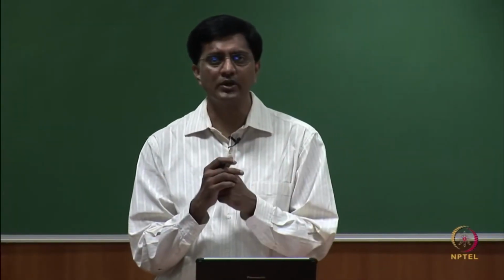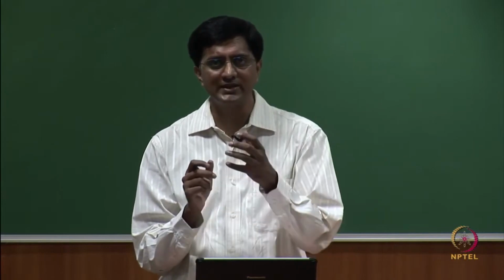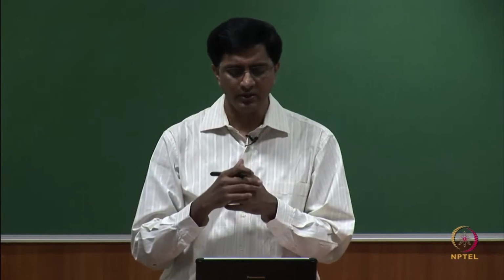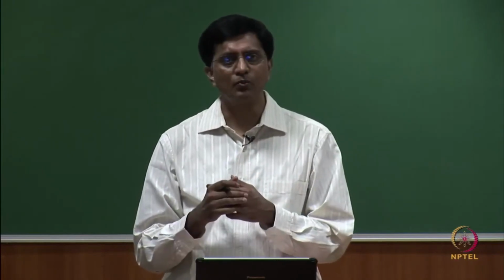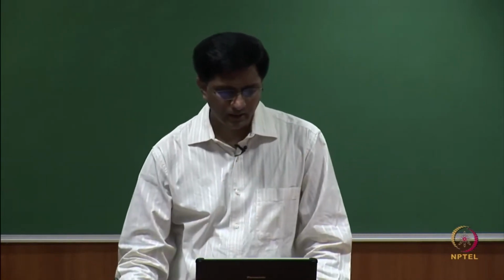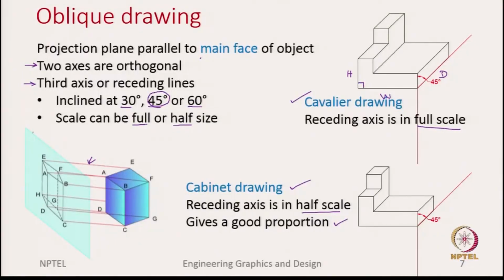And point to note is, cabinet gives a good proportion of the solid. So, it gives a good feeling of the solid, because as you can see, the Cavalier looks much longer, especially in the depth direction, but cabinet looks more realistic comparatively. So, I think I did not mention this, saying that the projection plane is parallel to the main face. So, this is the projection plane and this is parallel to, let us say, the main face here.